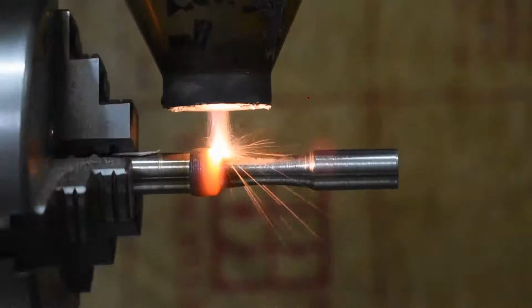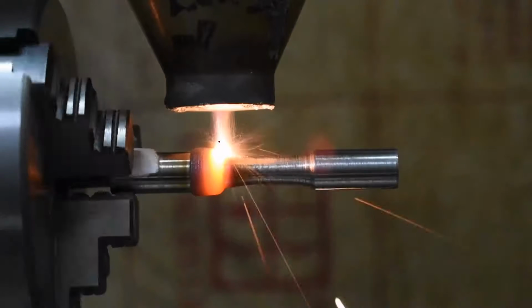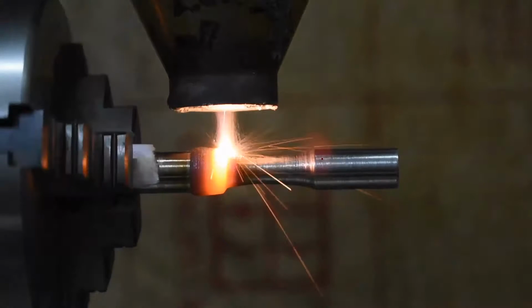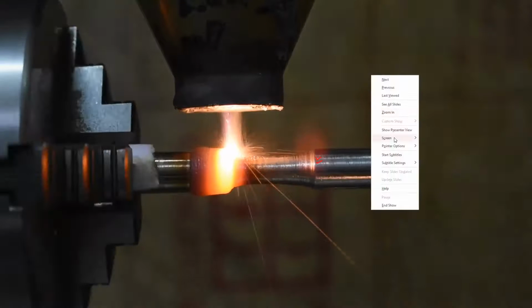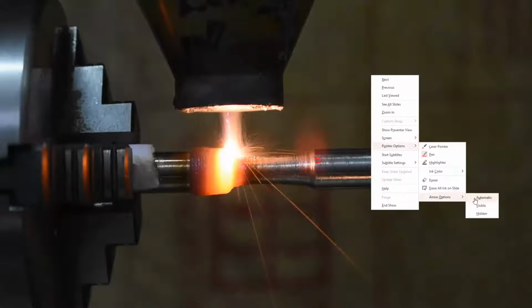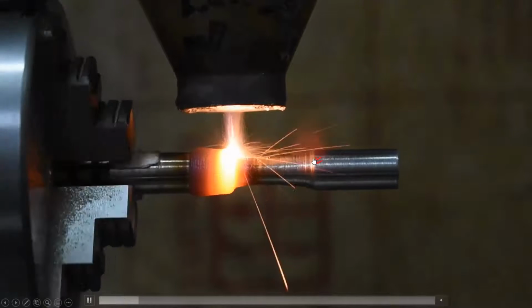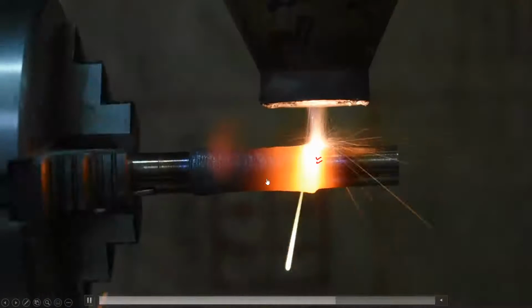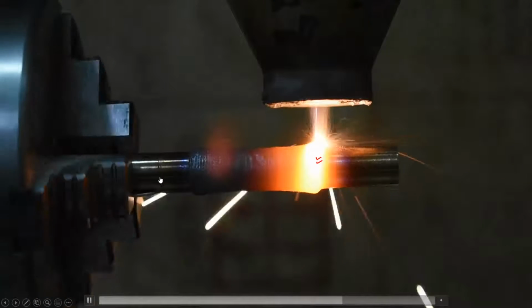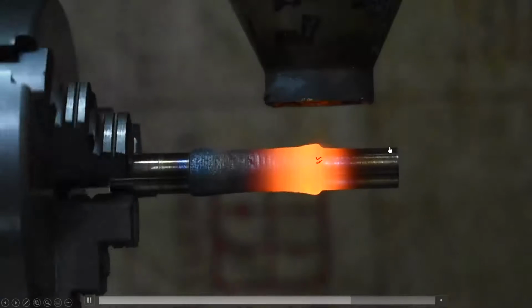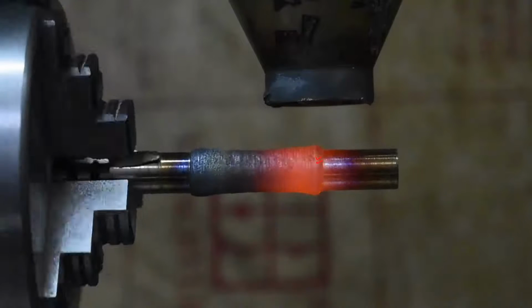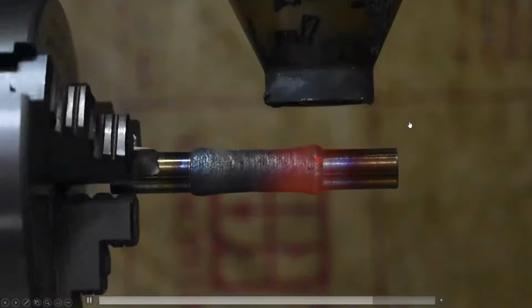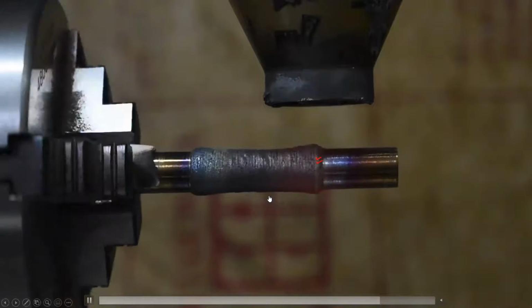The second one is heat accumulation. You see, when it is depositing, by the time it reaches over here, the whole component will become red hot. By the time it reaches the end of deposition, you will see the whole component is red hot, which essentially means all the properties of this particular shaft got changed. Complete recrystallization or phase transformation occurs in the whole shaft, which is not at all good. This is not something which we are supposed to do.